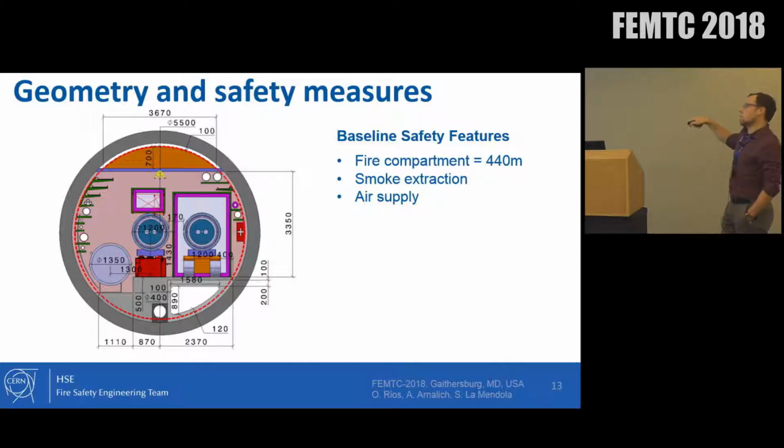It has this even surface, and then we have the ventilation compartments. Luckily enough, we got compartments every 400 meters. So we will reduce our simulations to these 400 meters. Actually, I never thought of having 100 kilometers simulated in FDS with a ring boundary condition. We rather go for a partial simulation of these compartments.